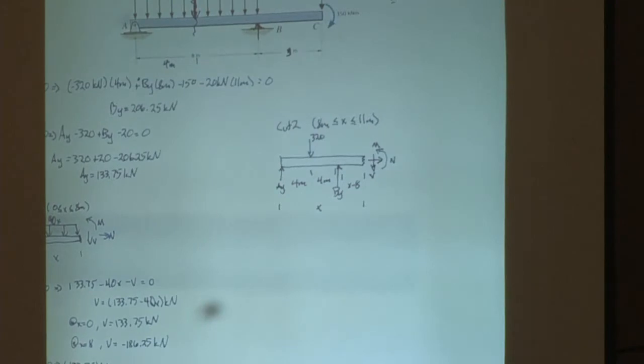Does that make sense to everybody? Anybody have any issues with what I did? Because we're doing method of sections. If you were focused on integrals, you would only have to do that section. So with integrals, you're only concerned with that line at that point, but when you do sections, you have to incorporate everything else. So you could have taken the cut from the right too, but I'm just going to be consistent and make the cuts from the left. Any other questions? All right.